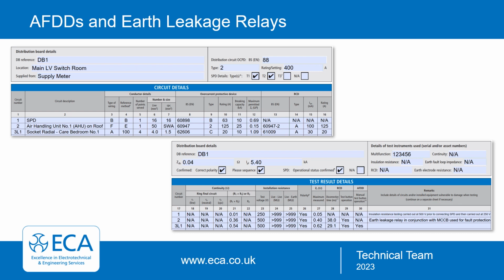So what about new technology and documenting that? Well, that should now be easier, and this is why these forms have been split over 2 pages. Let's look at the increase in use of SPDs, earth leakage relays, so RCDs, and AFDDs. And these are typical examples we're going to give here. So these forms give you a lot more scope. This is not in any great detail, this is just an example of how to use the forms, and they'll be open to your own interpretation.